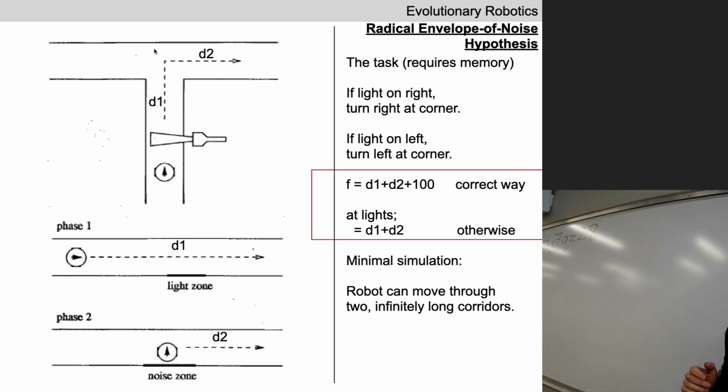Simulating a robot that's emitting infrared pulses in an environment that might look relatively simple here, but there's a bunch of corners here. It's tricky. Light starts to bounce around. If the evolutionary algorithm starts to evolve controllers that rely on reliable infrared sensors in this zone, it's definitely not going to transfer to reality.